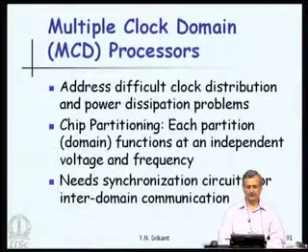It is well known that in a large CPU or large chip in general, supplying the same clock to all parts of the CPU is very difficult. It is not easy. It is simpler if separate clocks are used in different parts of the CPU, but then clock synchronization between these is a very difficult problem. So, it is not easy to use such processors.